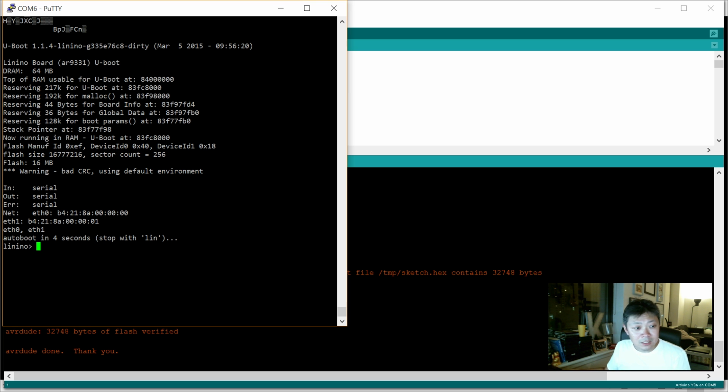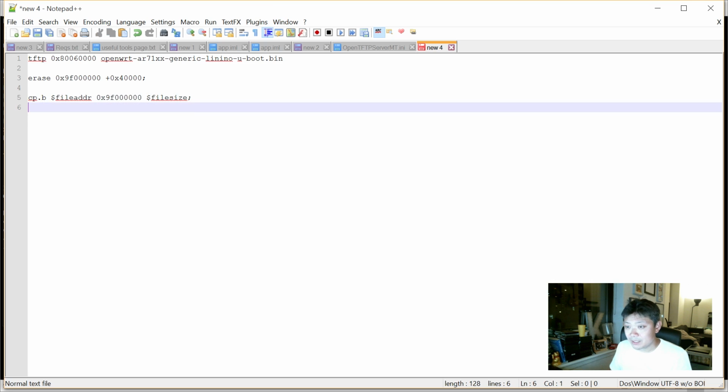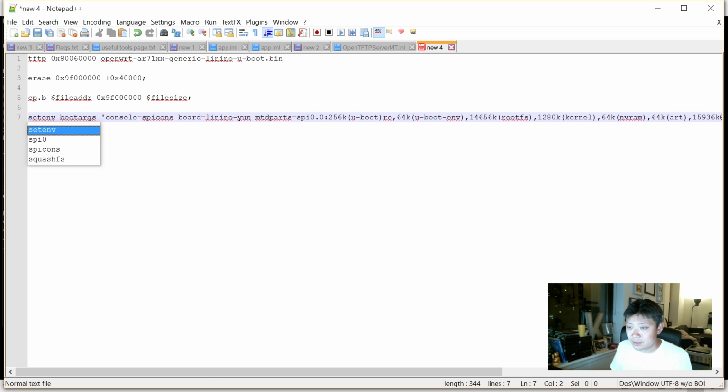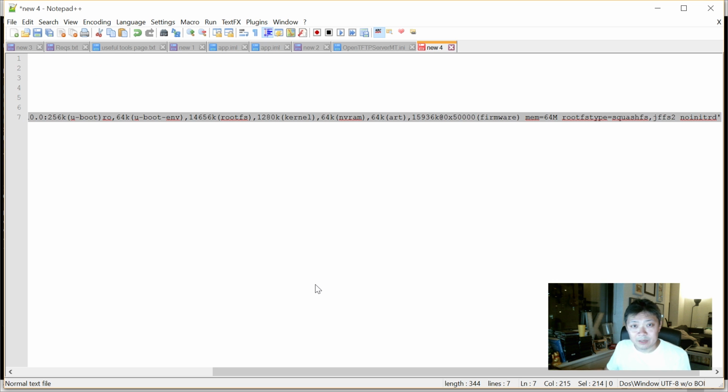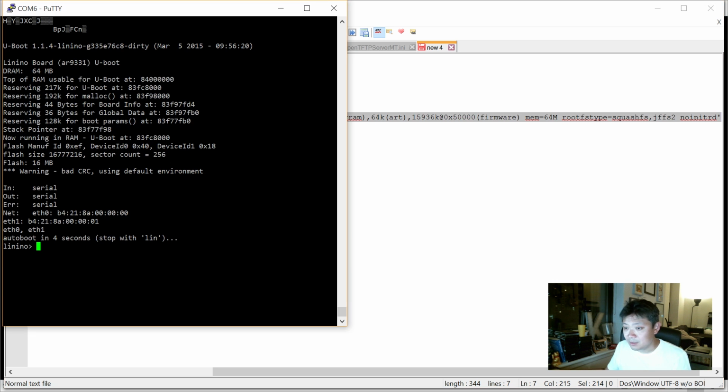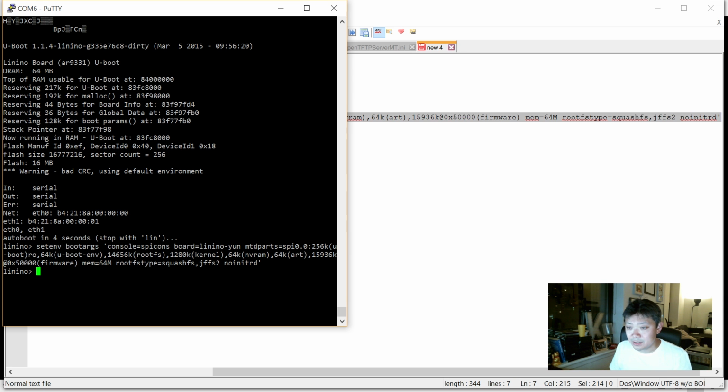Okay. Great, so now we're going to run a few more commands, and this one again I'm just going to copy and paste because it's just so prone to error. Pop it back into the notepad. Again, this command will be on the site. Then I'm going to paste it in there. I'm never going to remember this command. Just saying. Okay, next thing you're going to do is set baud rate 250.